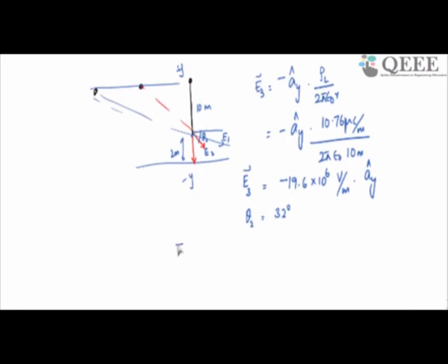So, I can calculate E2 as 10.76 microcoulomb per meter divided by 2 pi epsilon naught. Here it was 10 meter, corresponding to E2. I already told you what was a calculated value. That was something like 18.9 meter. So, this is 2 pi epsilon naught into 18.9 meter.